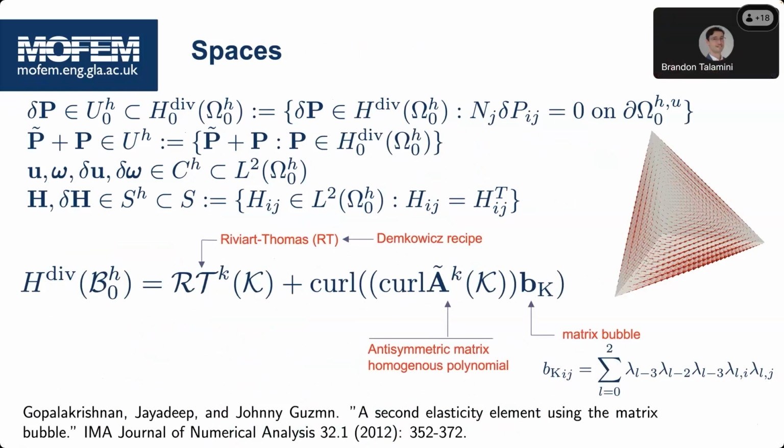What you can do is, because we have this symmetric version of the formulation with a block structure, we can condense to the rotations only and study the Hessian, what happens with its eigenvalues. And when we see instability, for example, we can add relaxation in time in order to pass this moment of cusping, wrinkling, and so on. This is what we try to do as well. But we see this mixed element as a toy which we haven't fully explored. There are many things you can do, much more than with the classical formulations. Yeah, thanks. I see that.